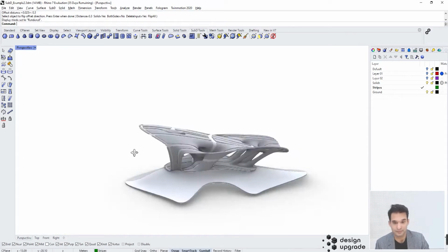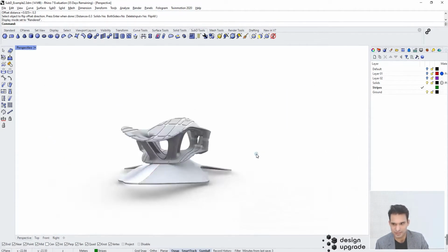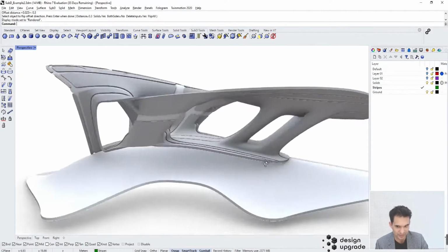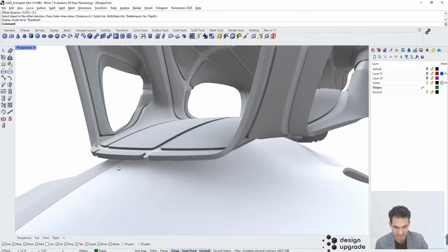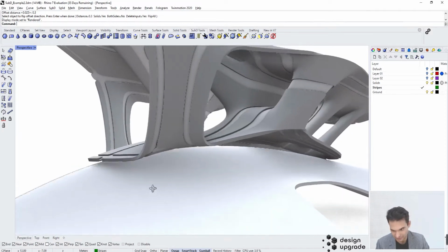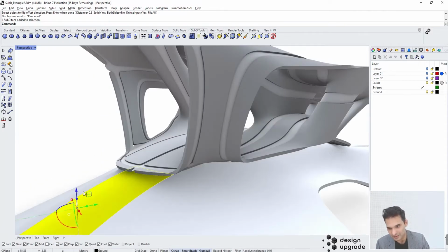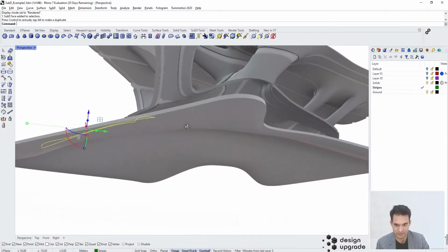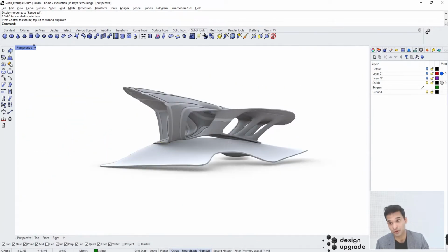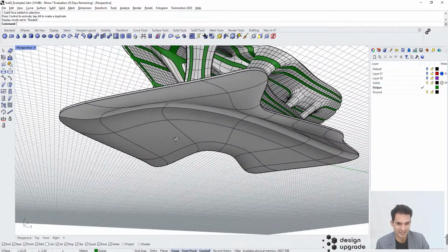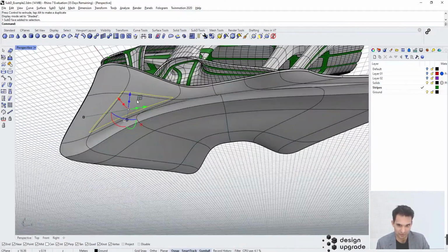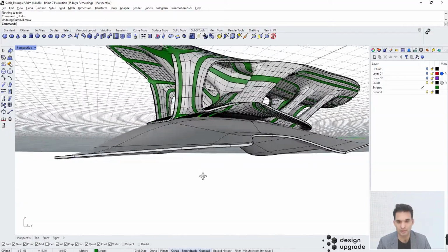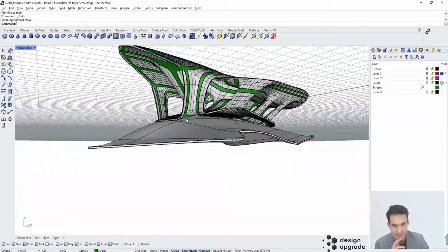Let's have a look. That does look kind of interesting. Yeah, I mean, we could have designed that a bit better so it's more extreme, but I like that it only has 2 points where it rests. Now there's a good question. If you push this guy up, does it still work? It does. So you also have control on your solid SubD. You need to select both faces if you want to have an equal offset. Otherwise it will just offset the upper, not the bottom layer. So that's very important to note. But I think that's good.